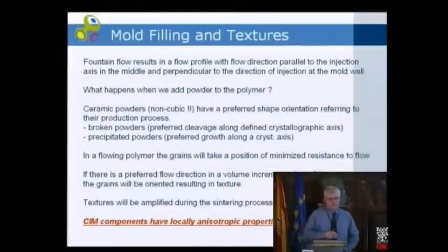So what does this mean? This fountain flow results in a flow profile with a flow direction parallel to the injection axis in the middle and perpendicular to the direction of the injection at the mold wall. So this was thermoplastic injection molding just with the polymer.